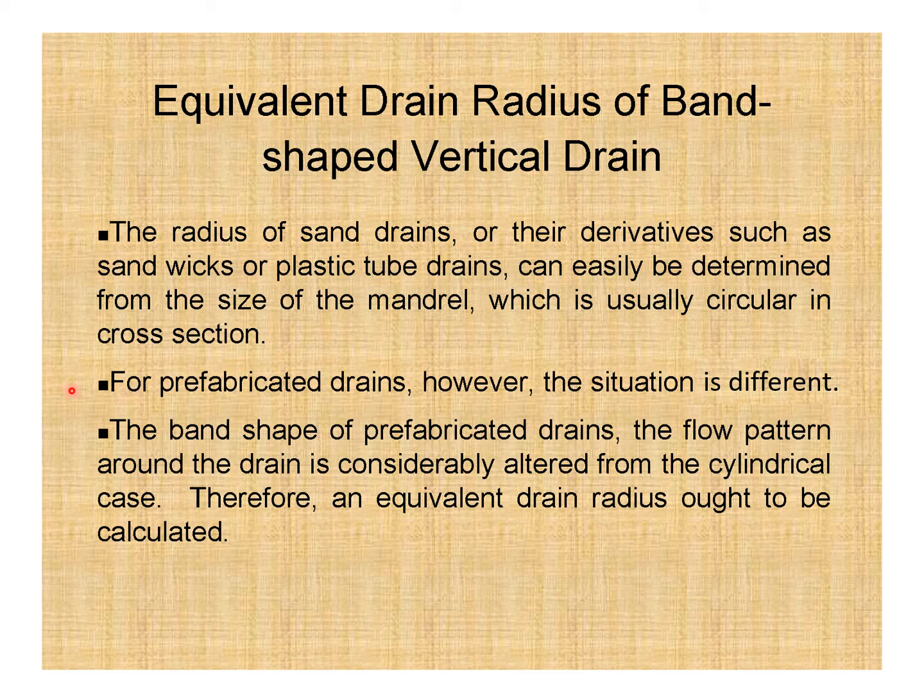Okay, for prefabricated drains, however, the situation is different. Because of the band shape of prefabricated drains, the flow pattern around the drain is considerably altered from the cylindrical case. Therefore, an equivalent drain radius ought to be calculated.